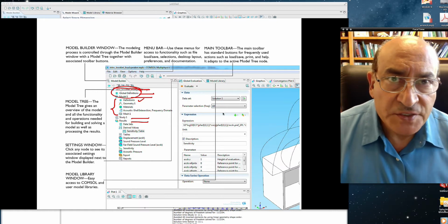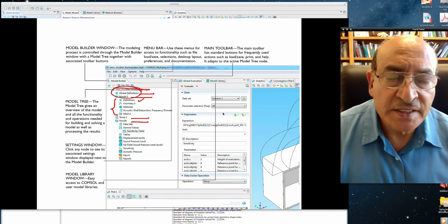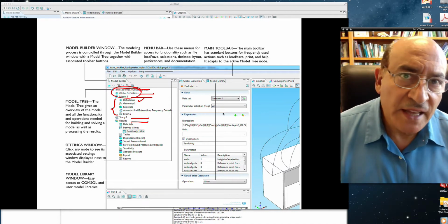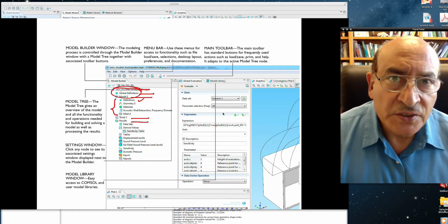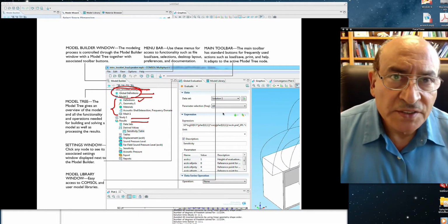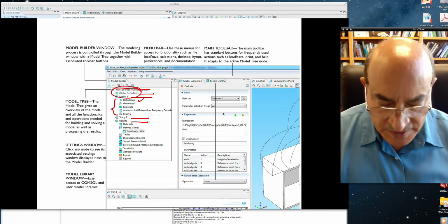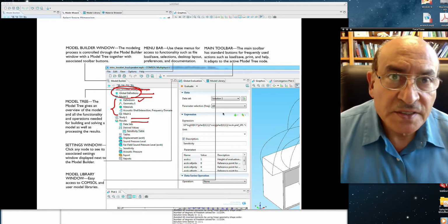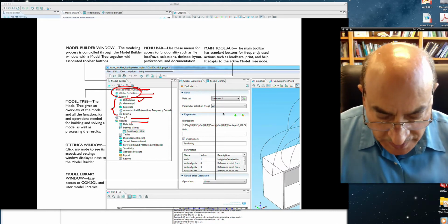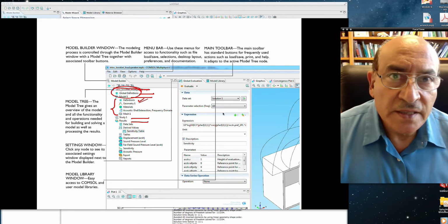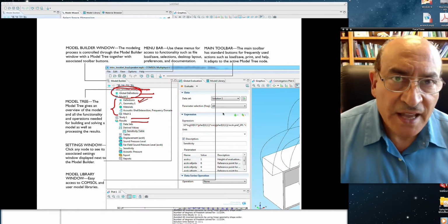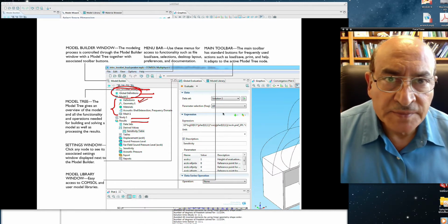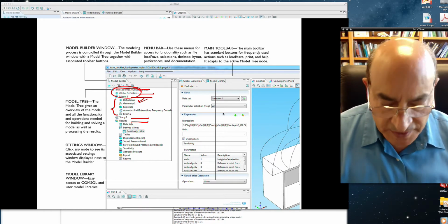However, if we have specific definitions of parameters that can be used in the model and then forgotten after we exit from that model, then we can redefine them in the child node of the model. So if you look at the model node, it has the following child nodes. It has the definitions, and then a geometry that you can either build in COMSOL or import from external file, such as a CAD file or even a prior COMSOL geometry file that you have generated.